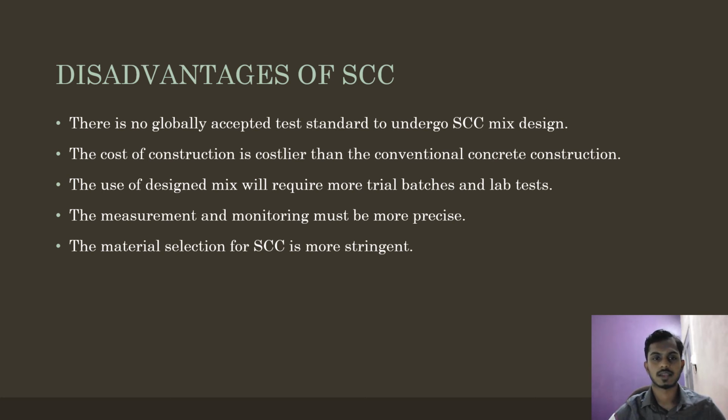Disadvantages of SCC. There is no globally accepted test standard for SCC mix design. The cost of construction is higher than conventional concrete construction. The use of design mix will require more trial batches and lab tests. The measurement and monitoring must be more precise. The material selection for SCC is more stringent.